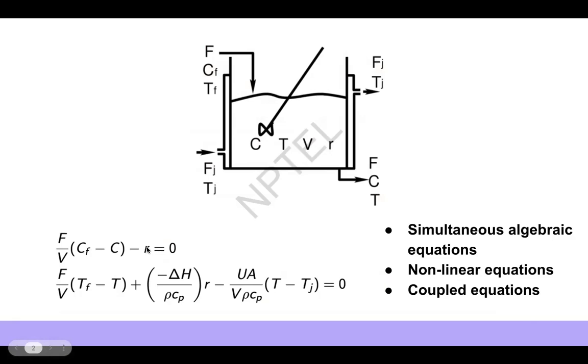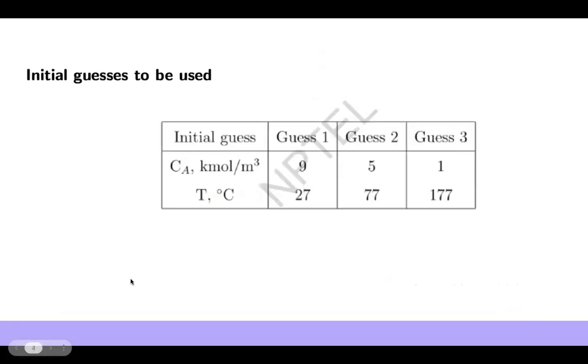When you have to solve a set of nonlinear equations, we use fsolve. fsolve is an inbuilt MATLAB solver that can deal with solving nonlinear equations. So we'll be trying to use fsolve. Also remember, we saw it last week, fsolve requires initial variables to be given. That is, if you're trying to solve for concentration and temperature, in fsolve you have to give an initial concentration value and an initial temperature value. Once that is given, these two equations are solved and you will get the steady state concentration and steady state temperature. That's what we'll be doing first.